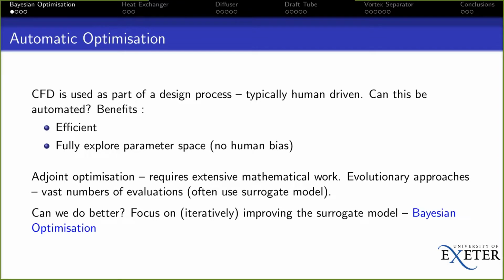Now, many of you are probably familiar with some of the approaches which are being investigated. Adjoint optimization is a significant aspect here, something which is commonly used in the automotive industry. And basically, you are differentiating the Navier-Stokes equations to find the sensitivity of your solution to changes in the design. It's a technique which is computationally reasonably cheap. Once you set it up to run, the adjoint system takes 1 pass through a solver, but setting it up